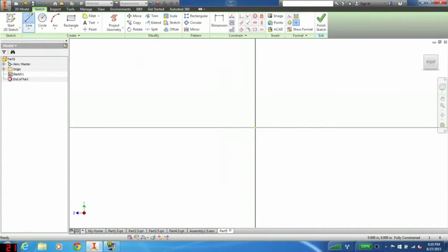So we're going to use the line tool because the L shape is much more complex than the rectangle. So we have 2 outer dimensions of 1.5 for the vertical and 1 inch for the horizontal. And when making a vertical line with the line tool, you click the first point to create the first point on the line, and then you can see that you can put the second point anywhere, and that will give you a line between those 2 points. So in order to get a perfect vertical, we're just going to move it so that it looks like it's vertical, and then you'll see that it will lock to 180 degrees, and we know that it is now vertical,